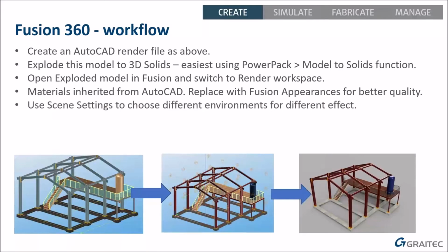You can use scene settings to change these environments. Some environments control all the lighting. The lights don't come from AutoCAD into Fusion. The environment controls the lighting, and the environment controls the background around your image as well. So different environments will give different effects of lighting and background. And then you do the render command.